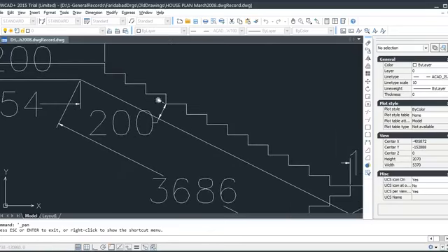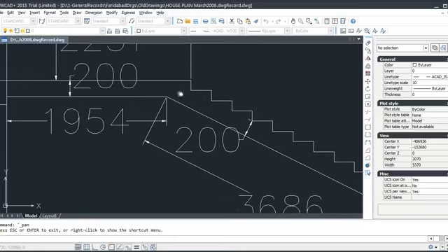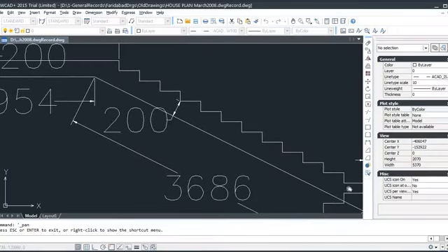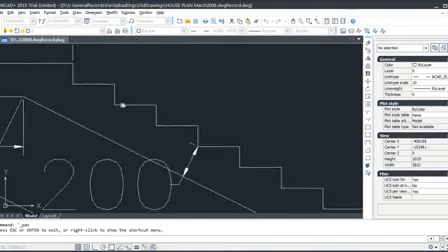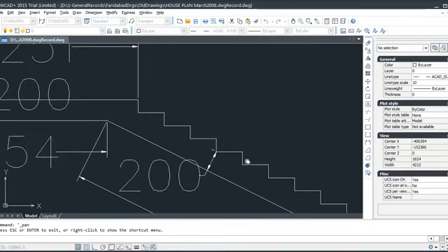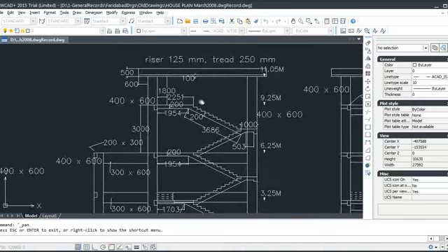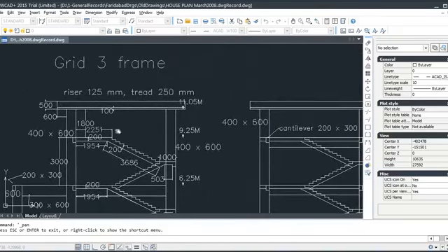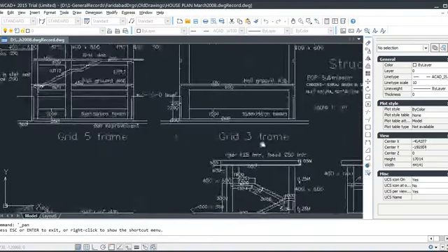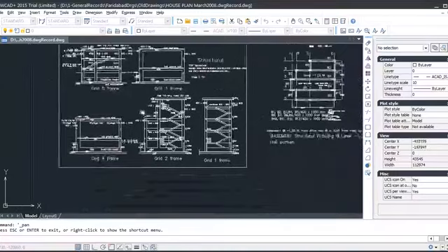Now it is better to take both up and down steel and make it like a beam, so that it doesn't fail. Similarly, make this waist like a beam, and provide steel in these steps also, so that your stair is monolithic with the framing. This is the basic understanding of how you can do it. And also I have shown these frames.